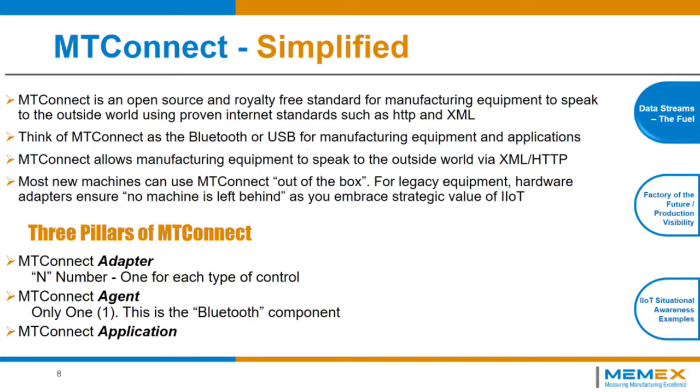Most newer machine tools, in fact, some machine tool manufacturers like Mazak, for example, have an upgrade path that is very long. Windows 95 controls can be upgraded to MTConnect, but also all the new machines can come with an MTConnect adapter. But for those legacy pieces of equipment, we have to have a hardware adapter that essentially turns the machine into a web server, and I'll have a slide on that. When you think about the 3 things of MTConnect, think about the 3 A's of MTConnect: adapter, agent, and application. In that order. Adapter is on the machine, agent is what serves the data to the application.